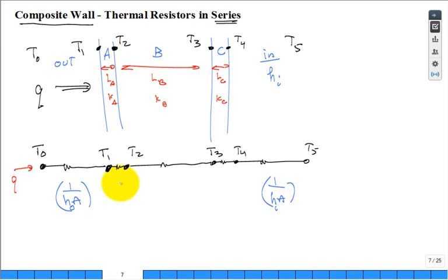And then we have 3 L over kA, L over kA, and L over kA. Those are 3 slab resistances. And we just have to say, okay, the first slab is length of material A and thermal conductivity of A. A little cumbersome because I have A for area and then I have A for that material. But you just have to pay attention. And then this is B, B, and this is C, C. So you have to use the thicknesses and conductivities of all those components.